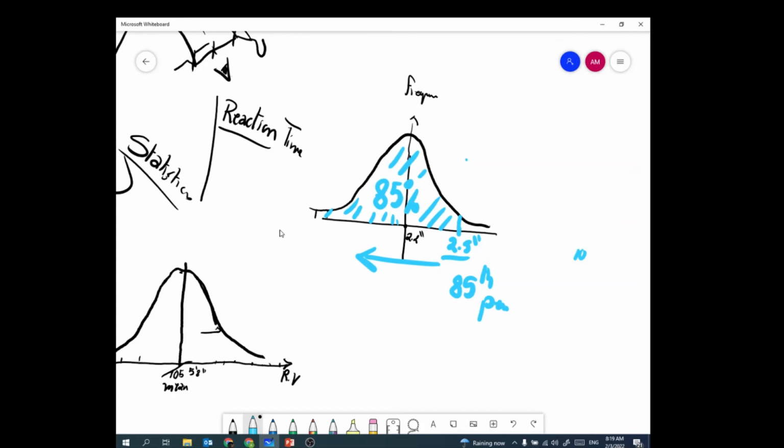So in this case, when I say my reaction time, TR, is 2.5, I here captured everyone that is faster than that. They're taken care of. Yeah, there are some outliers here that I did not take care of. And here comes the police and the enforcement, where they try to make these people slow down a little bit if they have really bad reaction time, and also the licensing process that will handle these people who are kind of slower in their reaction time. And here comes the law of giving licenses to people. So this is called the 85th percentile.